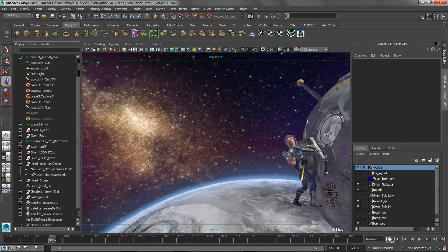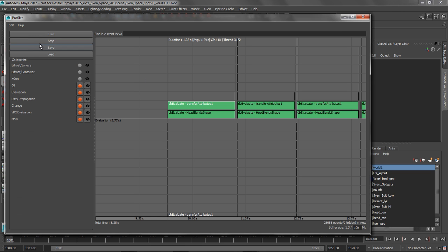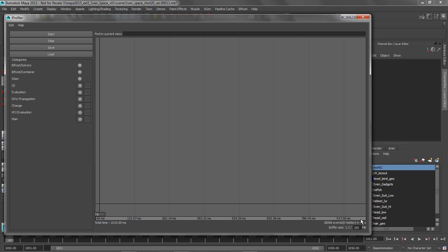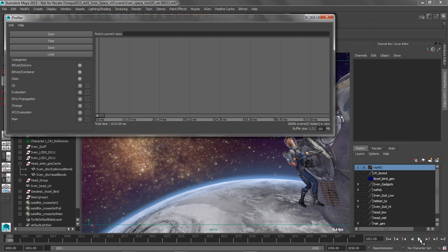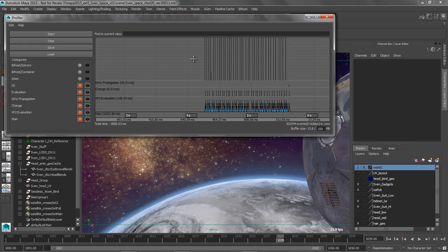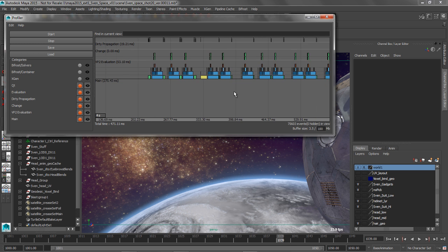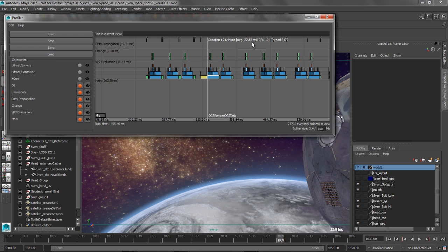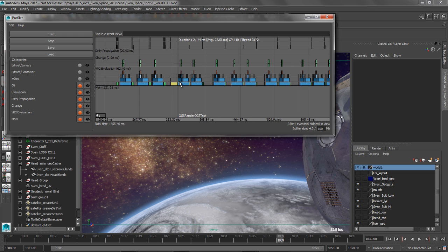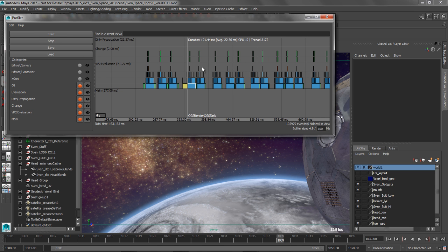and playing it back, obviously our frame rate's going to go back to being really quick. If we go back into that Performance Profiler tool and start it up one more time, hit play, stop it, you can see that now the frames tick off and there's just nothing there. We can see what's the slowest thing in here, but it's not going to be that. It's not taking that long. It's milliseconds. So it's a great tool for giving you insight into what's going on in your scene and helping you identify problems, fine-tune them and eliminate them.